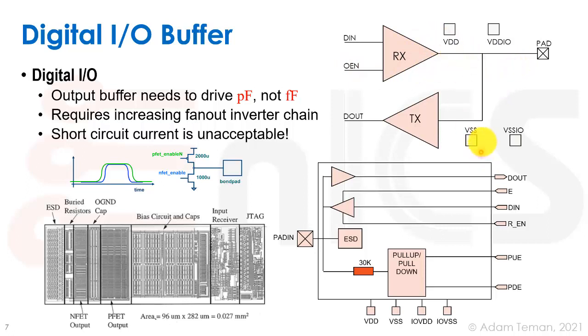We also usually have 4 voltages in this guy. We'll have our digital VDD and our core VDD, the VDD that we use inside the chip for the logic gates, and core VSS as well, which is usually 0 volts. Okay, and then we'll have an I/O VDD, which is usually a bit higher voltage. It used to be something like 5 volts, went down to 3.3, 2.5, 1.8. Nowadays, it could be maybe around 1.2 volts, and a VSS I/O, which is also going to be ground. Sometimes these two guys are shorted. Why do we have 2 different voltages over here?